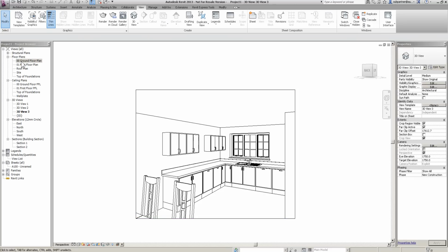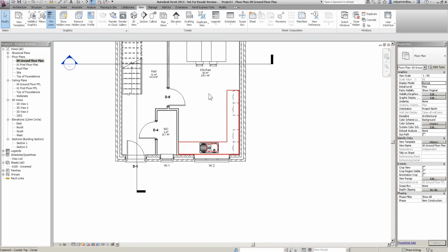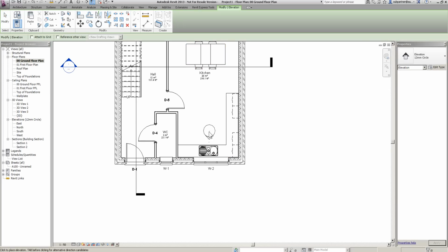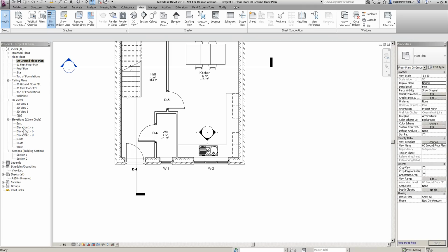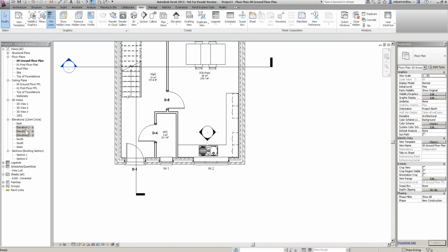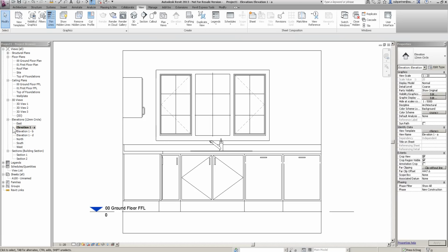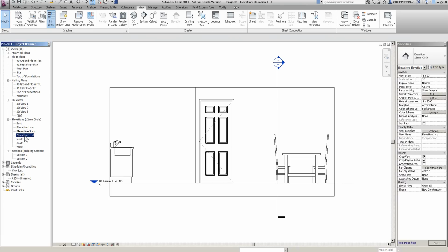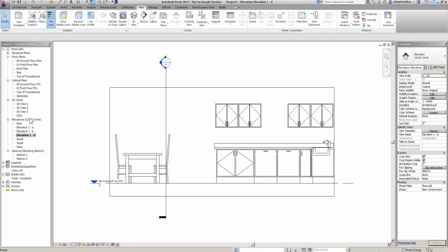Something I like to do is throw a little room elevation in here. We've all done room elevations for tiling layouts, etc. in kitchens. I'm just going to click there, turn that elevation on as well. You can see it's making elevations in here, like so. I'm going to make these elevations 1 to 20s. Fantastic. When I go into them, as you can see, we've basically got my room elevations for my kitchen. So you can start to put your tiling layouts on, all of that kind of stuff. Really nice and quick.